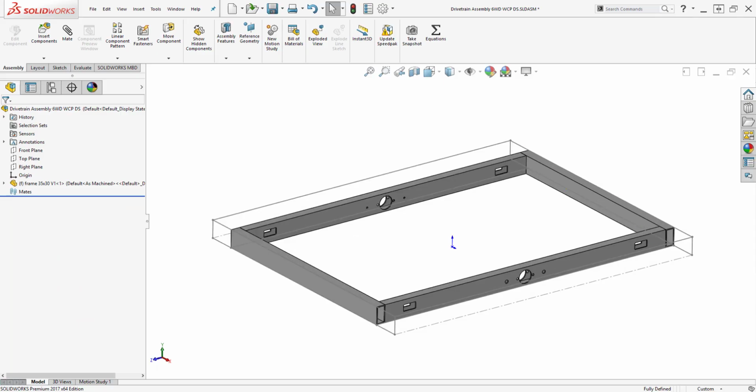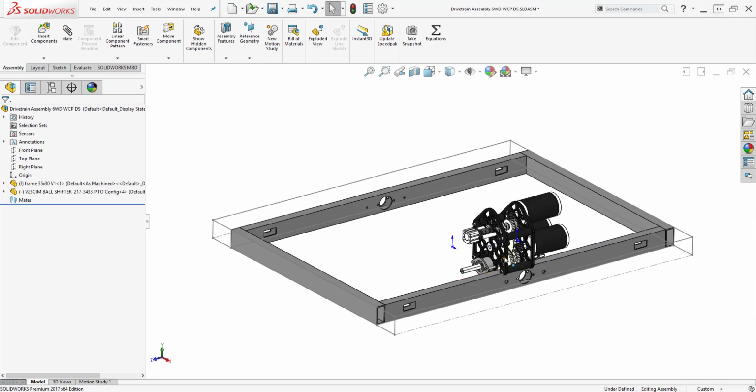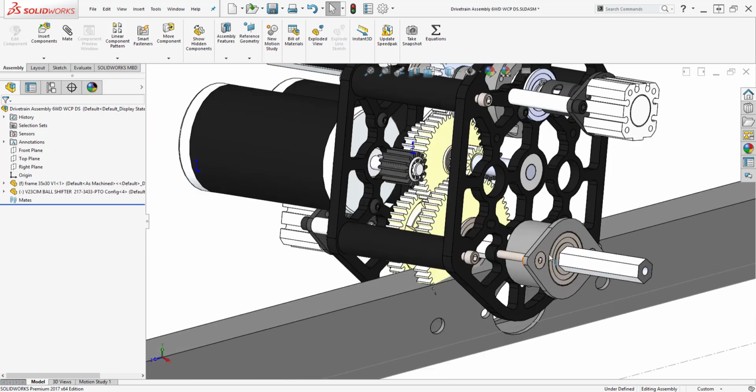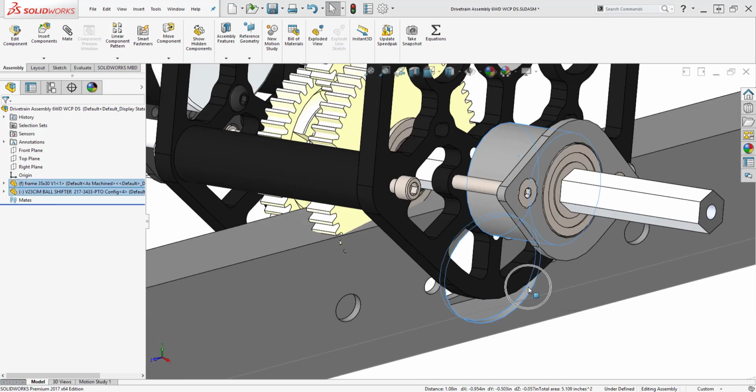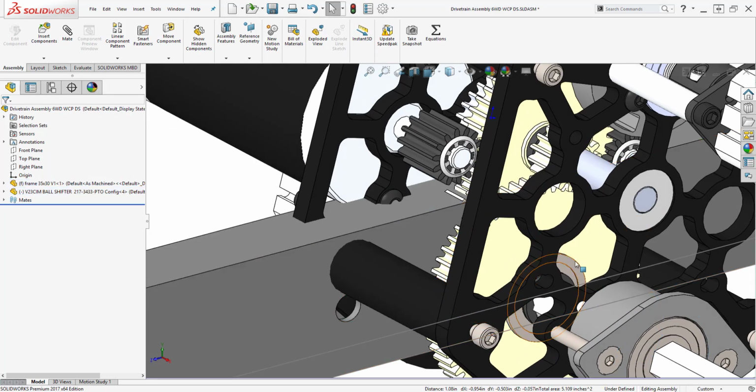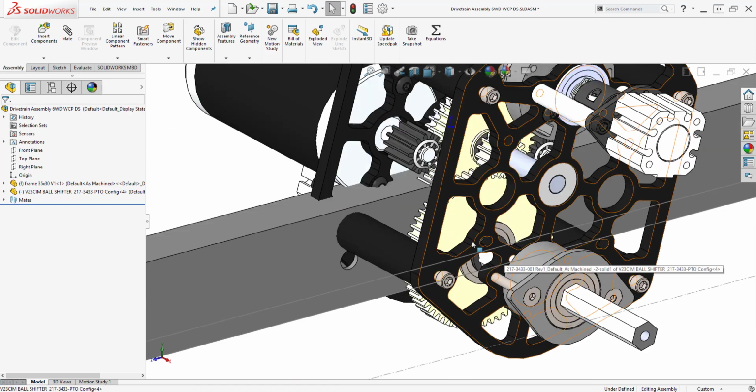With the drivetrain assembly, I'm going to focus on getting the gearboxes, wheels, bearing blocks, and chains sorted out right away. Drive system assembly frame first. Fixed, ready for gearboxes. Drop in one gearbox and we can build one side and then we'll mirror the other when we're done. Mounting the gearbox to check for hole alignment, everything looks good here.